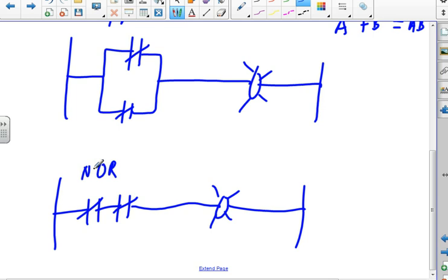Not only that, it was cut to the right length because the guy that designed it knew what length it was supposed to be, and it's bent correctly in the wire duct. So wire number 3-1 would go from X1 to the low level switch, and so on. So that's how I would label my wires exactly as the diagram is done.